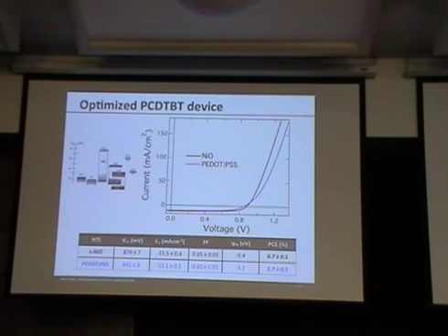I'm sorry, maybe I missed it before, but how did you coat the nickel oxide? Is it sputtered or solution processed? This is a solution process. So basically what we have is a metal organic precursor, and we heat treat that on top of the ITO. That converts it into a nickel oxide, I'll say that. One could worry about the structure, and I showed you that a little bit yesterday. But that's basically how we're generating it. And it's about 5 nanometers thick.